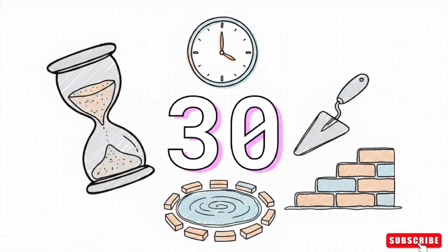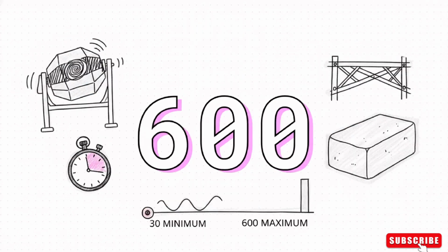This is a completely non-negotiable metric. The cement has to remain plastic for at least this long just to be workable on a busy construction site. And then on the other end of the spectrum, we have 600. The maximum final setting time should never exceed 600 minutes. Think about it. If it takes longer than that to harden, your entire structural timeline gets completely compromised.